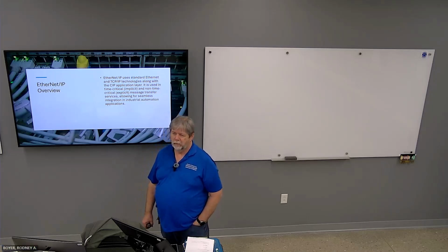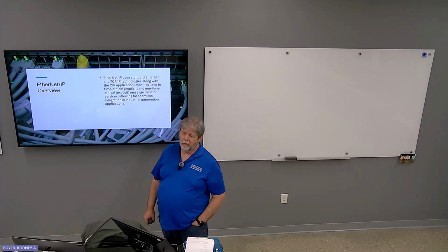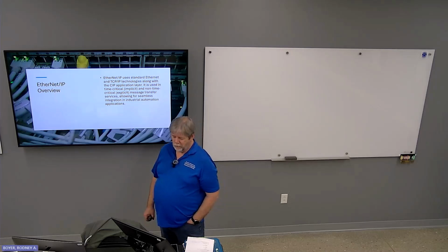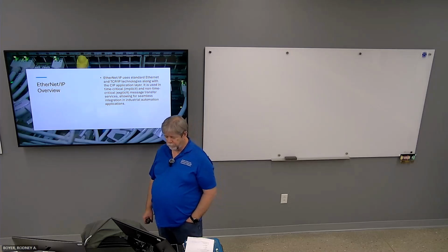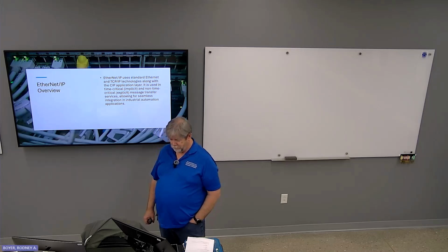Most communication between PLC and VFD is explicit messaging, because they're not necessarily time critical. It's just, hey drive, start, or hey drive, stop.